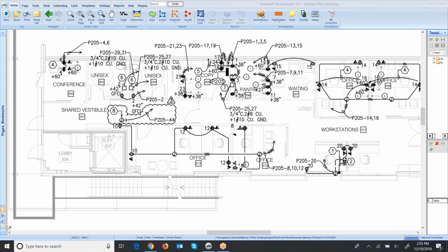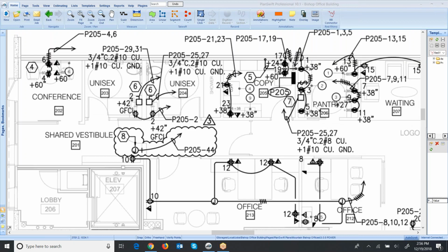This is a screenshot of a blueprint, or electrical plans, showing receptacles. Let me just zoom in here a little bit. Again, these are offices with receptacles in them. Let's just take a look over here. We see duplex receptacles and quad receptacles, right? Double duplex. We see data stub ups. There's GFI receptacles here. So using Red Rhino assemblies, you simply count these items.